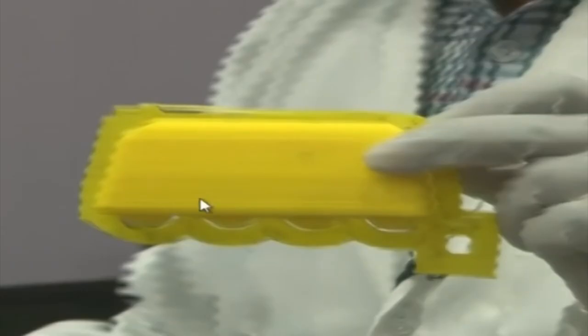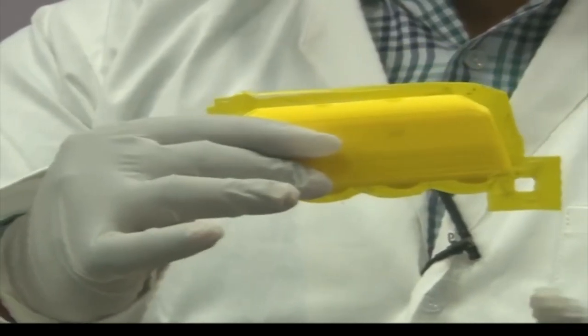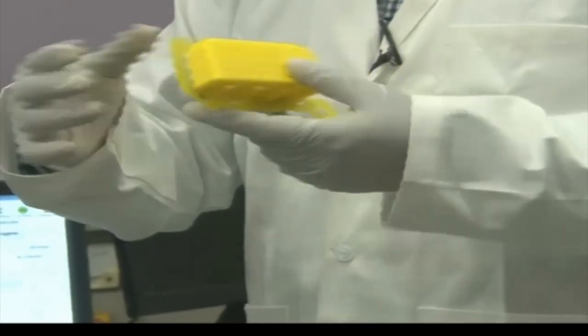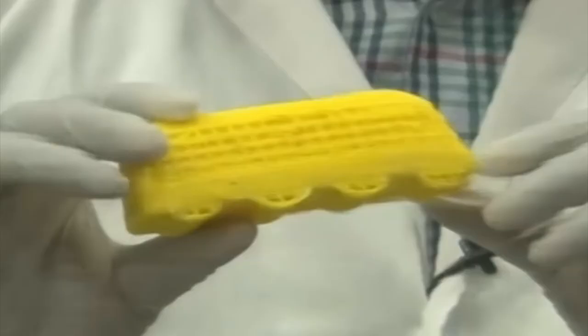Also we have more extra material here, those are supports, and we will try to show you how we remove them. We can remove brim by hand very easily, manually, and we can get the finished final product. If the CAD model is flat, it's okay. If it is not flat, if it has some inclination, what would happen? How would the machine take care of the printing? It would provide some support.